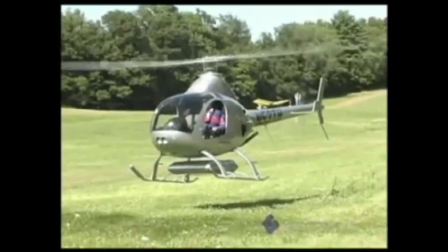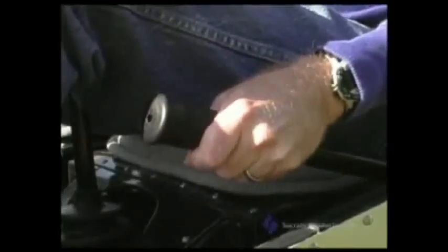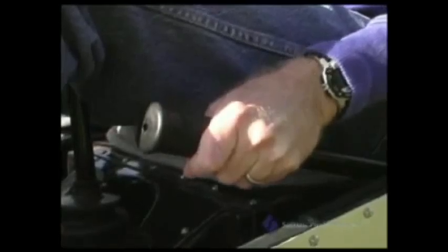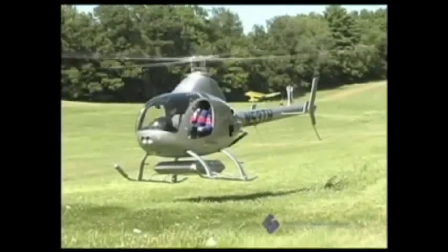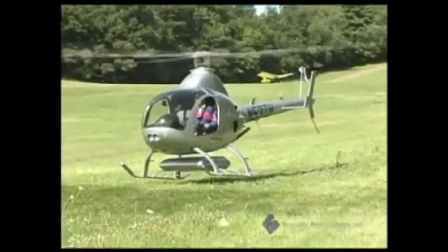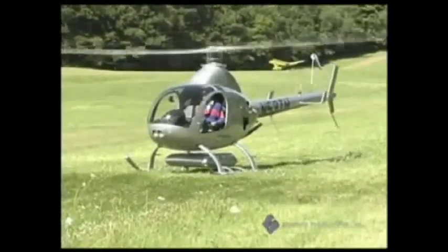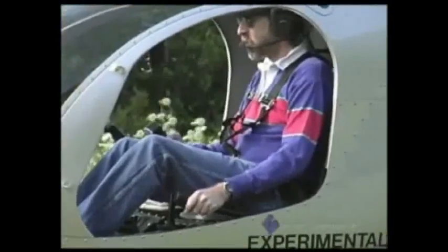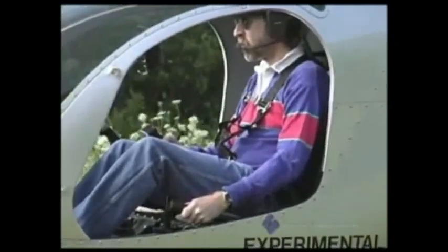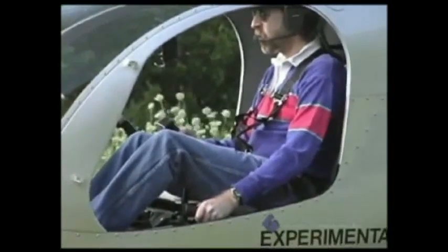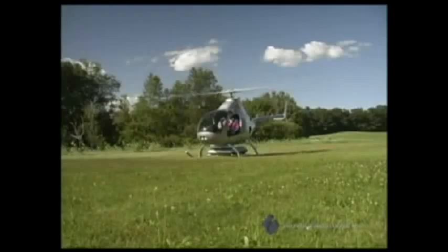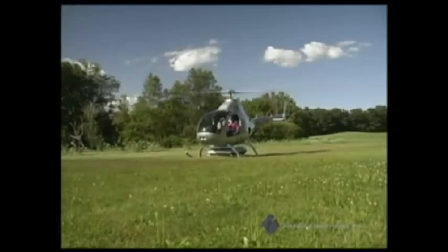If total rotor thrust is decreased by lowering the collective, less power is required and the throttle must be decreased. The throttle must be coordinated with the changes in collective. In some helicopters, the collective and throttle are mechanically correlated and only require fine-tuning by the pilot. All turbine and some piston helicopters have governors that precisely control the engine RPM.